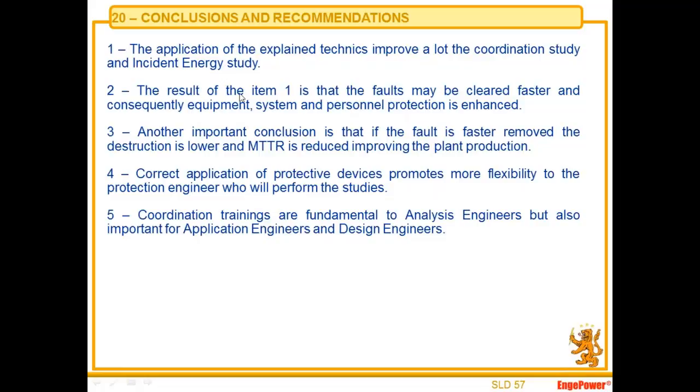As a result of item 1, the faults may be cleared faster and consequently equipment, system, and personnel protection is enhanced. Another important conclusion is that if the fault is removed faster, the destruction is lower and the mean time to repair is thus improved, improving the plant production.